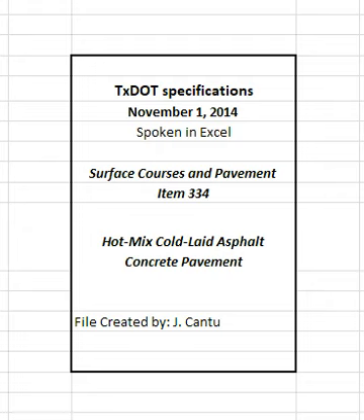Use a motor grader to spread the mixture when shown on the plans or approved. Thoroughly aerate the mixture and spread into place with a power motor grader in a uniform layer. Placement in narrow strips or small irregular areas may require hand spreading. 4.4.1 Weather conditions. Place the mixture when the roadway surface temperature is 60 degrees Fahrenheit or higher unless otherwise approved. Place mixtures only when weather conditions and moisture conditions of the roadway surface are suitable in the opinion of the engineer unless otherwise shown on the plans.